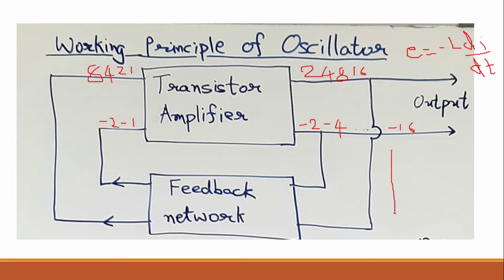Remember, from the output characteristics of transistor, which we have already seen in our transistor common emitter characteristics, input output characteristic. For the output characteristics, this is VCE and this is IC, the output current, for different values of IB. So you can see here, or you know that after some particular level the collector current becomes constant.